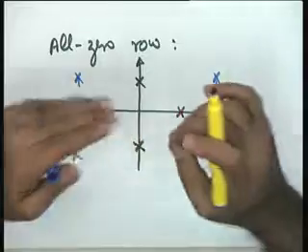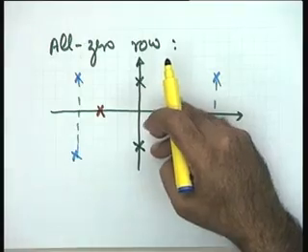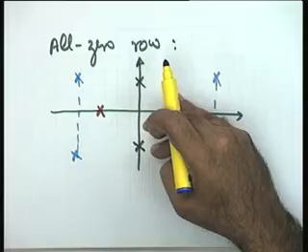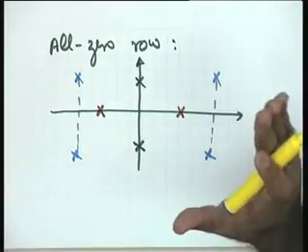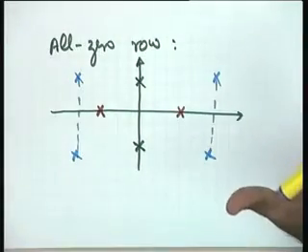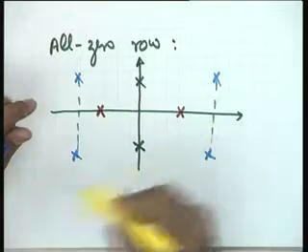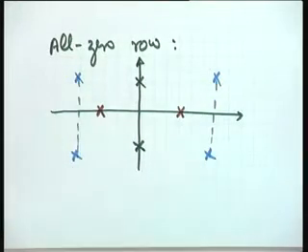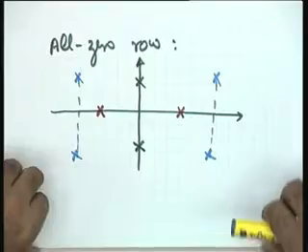So, you see that if you come across an all 0 row, nothing can be said, all these possibilities, even multiple roots, are possible. There may be a multiple imaginary axis root, in that case the system will be unstable. So, the only thing is that you have to further analyze this particular system, because when you come across an all 0 row you cannot make a statement on stability of the system. Okay? Let us see how we study that.